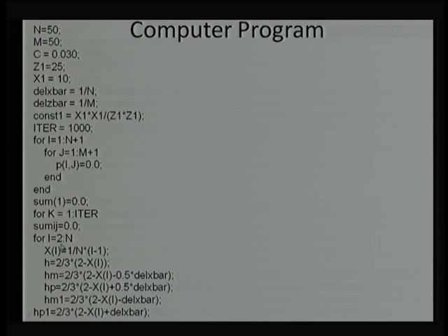You say for I is equal to 2 to n. Keep in mind we are using the boundary condition. We know the nodal pressures at the first node as well as the n plus 1 node. Initial and final pressure is already known, that is equal to 0, that is equal to ambient pressure. So, using this kind of loop we are incorporating the boundary condition without any problem.